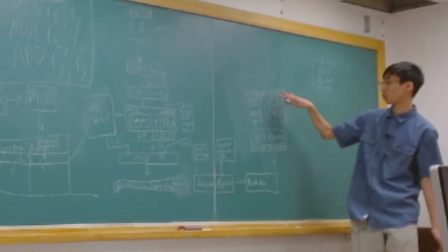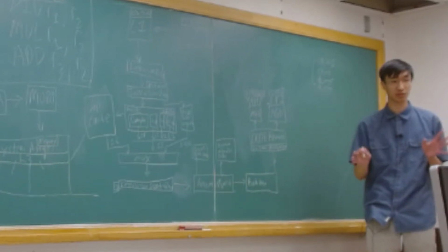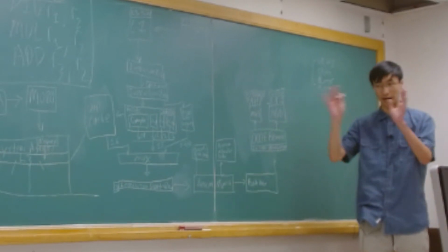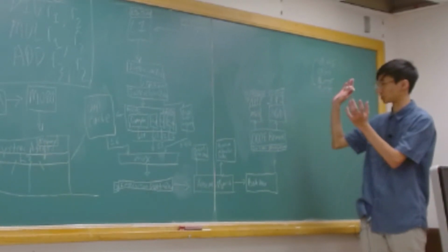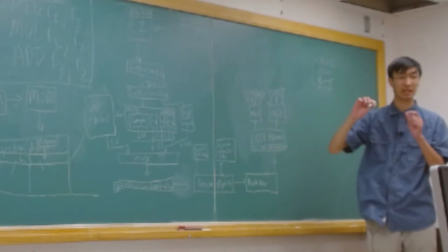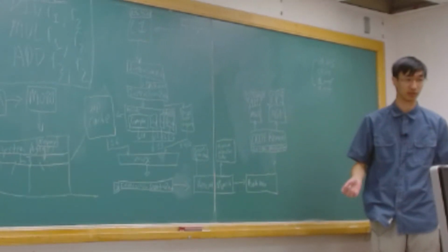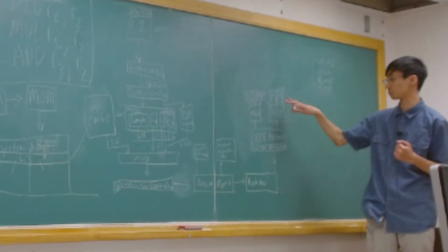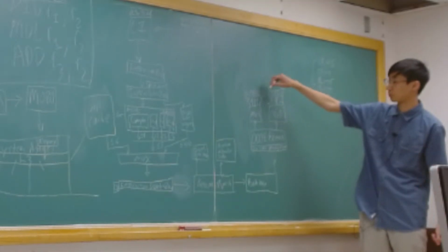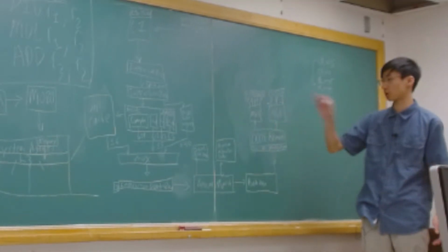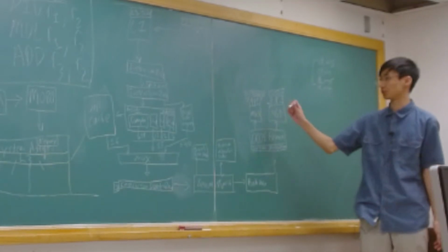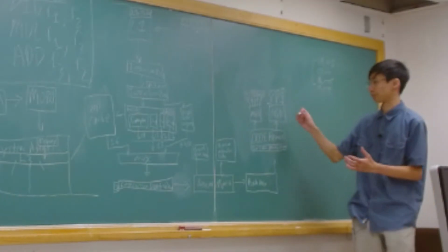These ports here will have address generation units, so they'll go and calculate addresses. You'll give them registers or something, and they'll go figure out what the address is. And then maybe you can also store things using them or load things. This is primarily usage of it. Number 4 will do storing as well. It's just part of the math scheduler because you can do, we'll talk about that in a second.